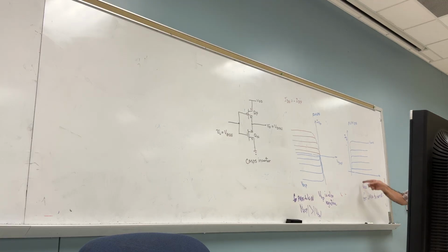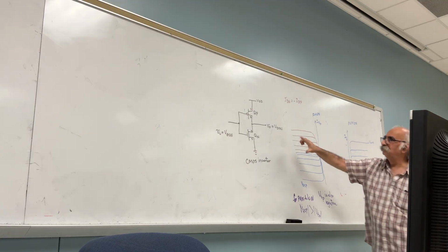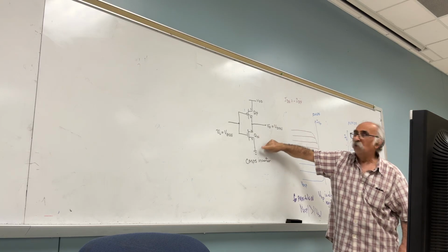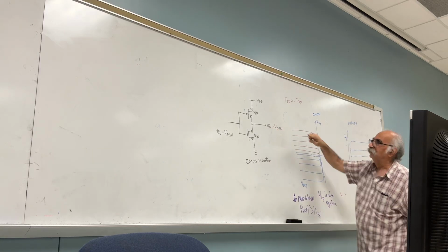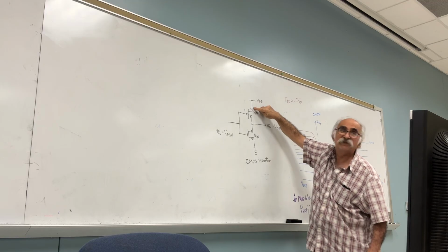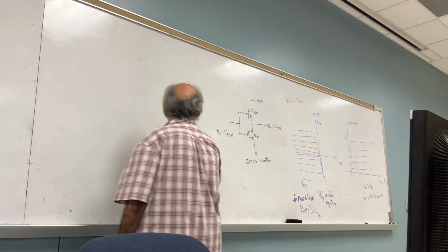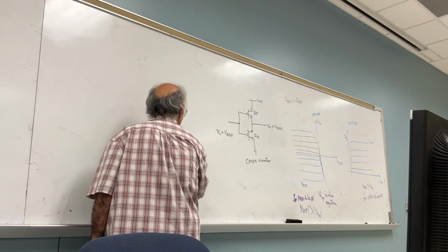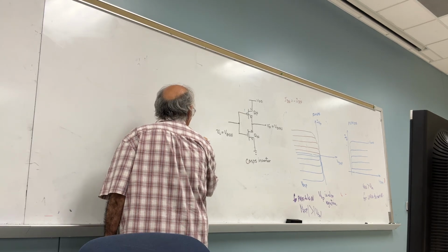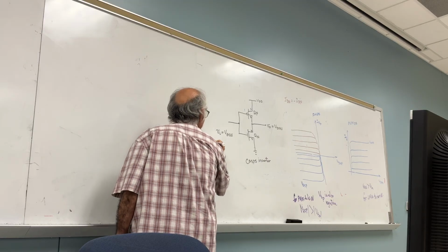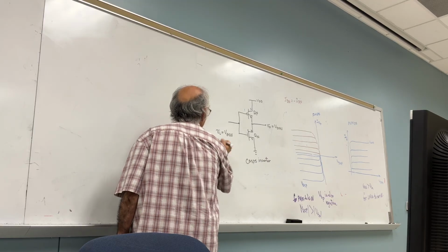Yes? Let's see. Where is the VDSN? Is the voltage between this one and this one? Yes. Where is VDSP? Is the voltage between this one and this one? Yes. So what can I say? VDSN is equal to what? VDD plus VDSP.